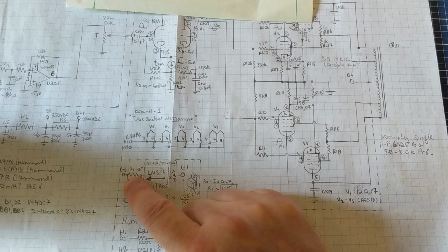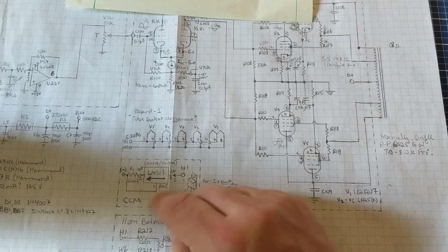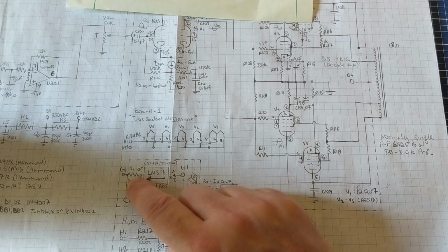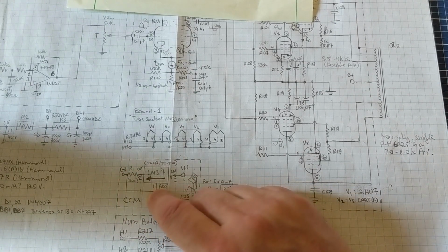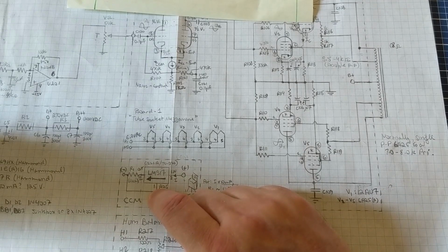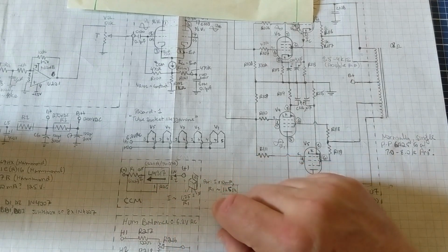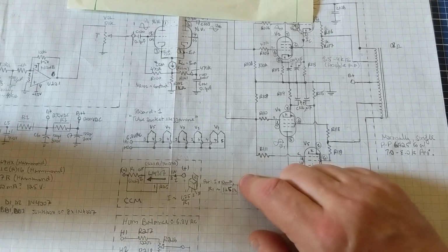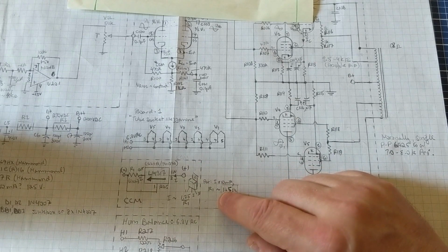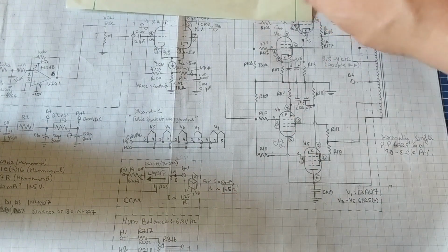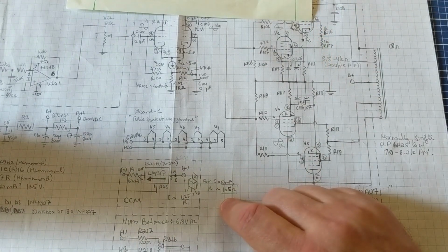R1 is the resistor separating the voltage input point from the adjust point. Sorry, this is the output of the regulator. So the output of the regulator goes through a dropping resistor, and the other side of the dropping resistor is used for the adjustment voltage of the 317. So for example, for 10 milliamps, the resistor would be 125 ohms. And in our case, we want 5 milliamps, so the resistor would be 250 ohms.